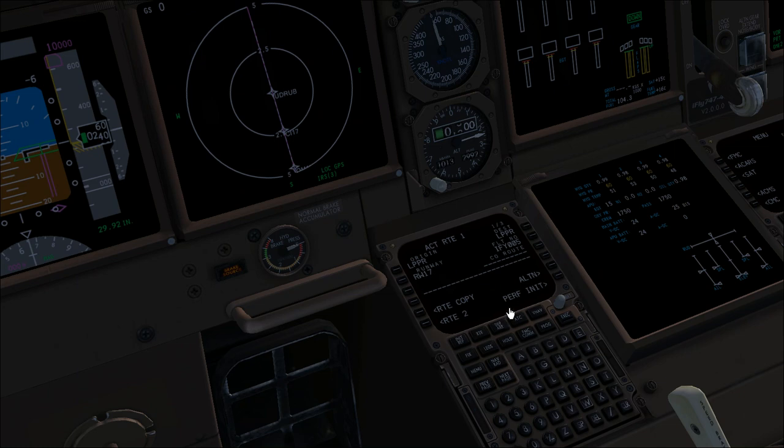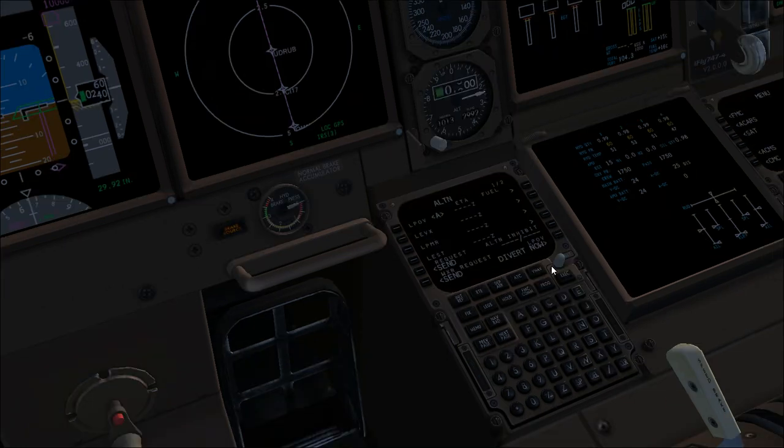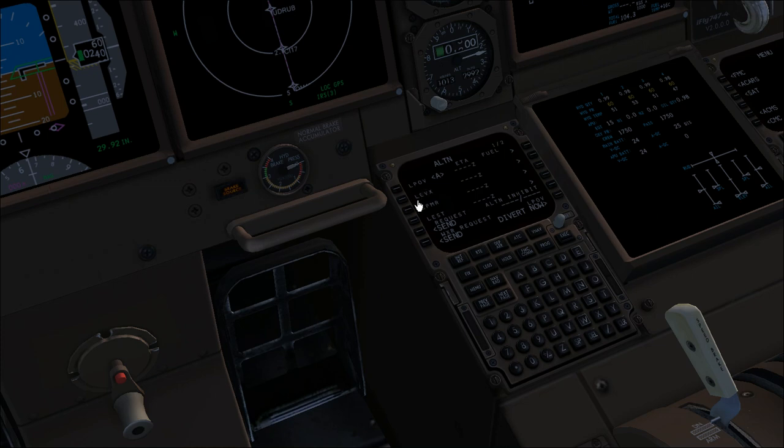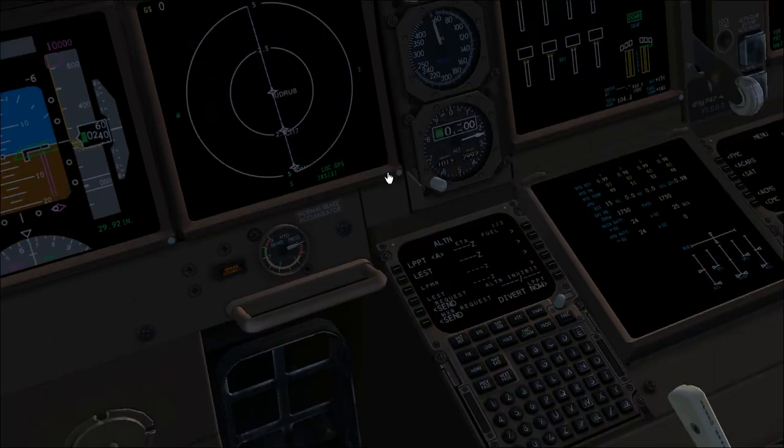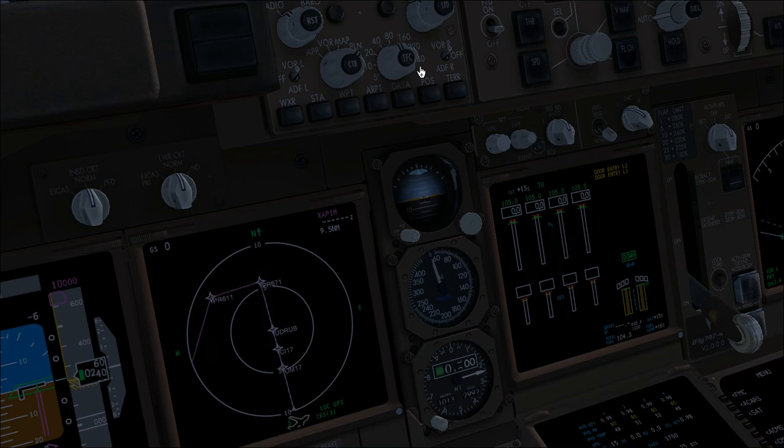We can return to the route page now and set the alternate airports. In the alternate airports page, those are actually in small letters. Those are actually automatically selected. You can make it manual, selecting, for example, this is Porto, selecting Lisbon, for example, Lima Papa Tango, and start on the first line. Or you can select, for example, Santiago, that is also in the list. As you can see, we can select it, and now we have two alternate airports selected.